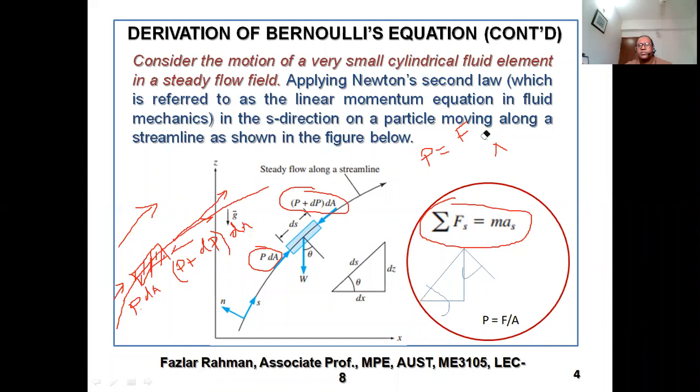If you know the volume, then you multiply by density, you'll get mass. Then you have mass, multiply by g, you'll get the weight. For example, this one, figure out the volume. Area we already have. The cross-sectional area is dA. What is the length of the fluid element? ds. So you multiply by ds, you get the volume.